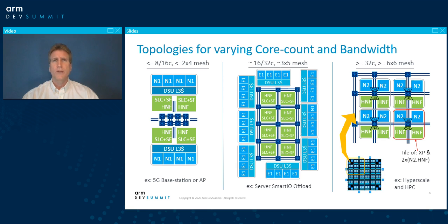Well, after building many internal CMN-based reference designs in-house, we've come up with several general guidelines for component placement. Generally, we advise placing the system cache, also called home nodes, and CPUs close together around the interconnect, and then place the external memory and I/O out around the edges. We found that this provides the lowest average latency and even traffic load distribution.